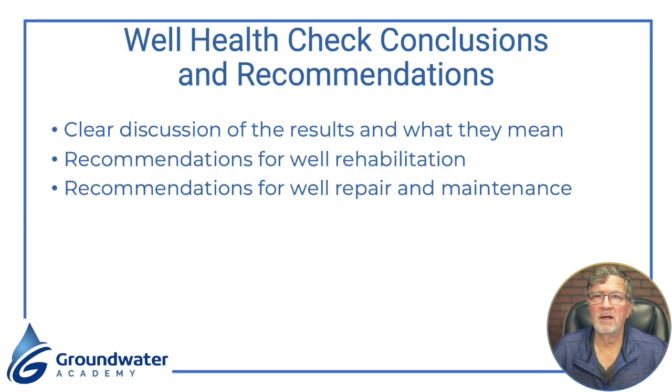All right, so you're going to look at all these things. You're going to look at the parameters. You're going to look at green, yellow, red, and you're going to come up with recommendations for your well rehabilitation based on what problems you have and make those specific to the well. So you're going to basically come up with a recipe that you're going to give to the well rehab contractor. And I tend to prefer well rehab contractors that specialize in well rehab as opposed to drillers that just kind of do it as a sideline. You're going to get much better results. But you're going to want to have something that's specific to the problem you have identified in the well.